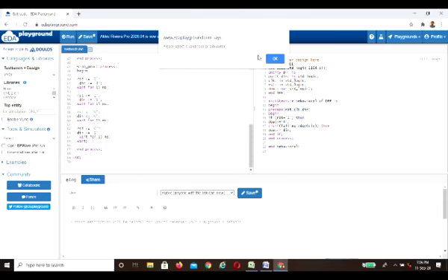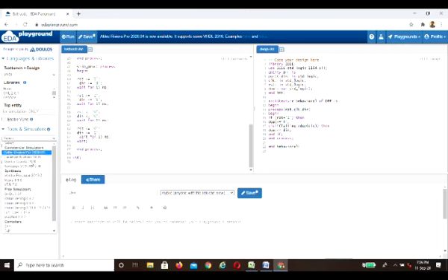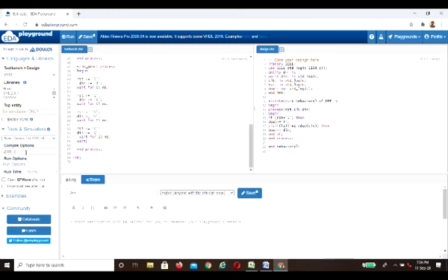Select a valid tool simulator. On the left hand side there is a tools and simulator option. If you click on this drop down arrow, there are a lot of simulation options. You can see Mentor Graphics, Cadence, Synopsys, a lot of options. But in the case of VHDL or Verilog, you can choose the basic default simulator, Aldec simulator. So you just choose Aldec simulator and save your program with this DFF name.